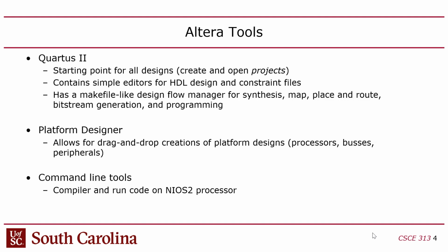But anyway, my point is when we went to the 4-core processor, you would basically have to have 4 Eclipse projects, because there's no operating system. So whenever you link your binary file that you download to the processors, they would have to be linked for the specific memory regions that each processor would occupy. Otherwise, they'd step on each other, right? So you had to have 4 ELF files, 4 binary executable files that you would then offload to all 4 processors. Because unfortunately, in bare metal, that's the only way to do multi-core.